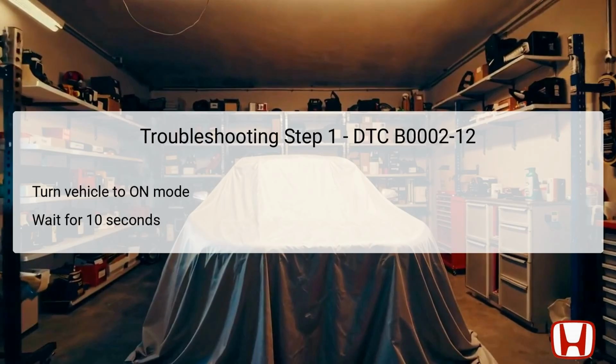After waiting, the technician should check for the presence of DTC B0002-12. If the code is still present, it indicates further investigation is necessary, specifically focusing on the driver's airbag and its associated components.